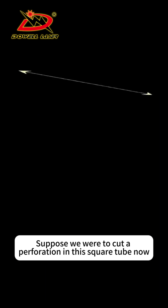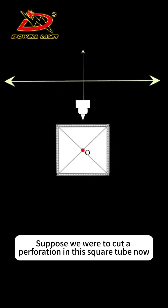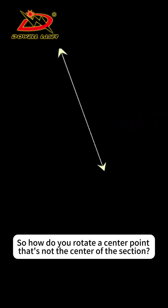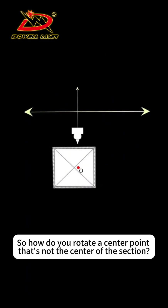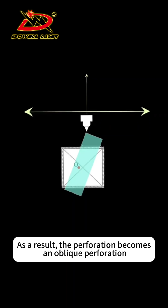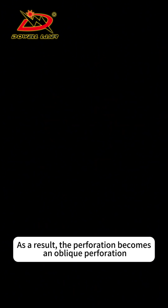Suppose we were to cut a perforation in this square tube now. When we look at the chuck, the cutting head moves like this. So how do you rotate a center point that's not the center of the section? The travel distance of the cutting head on the x-axis is constant. As a result, the perforation becomes an oblique perforation.